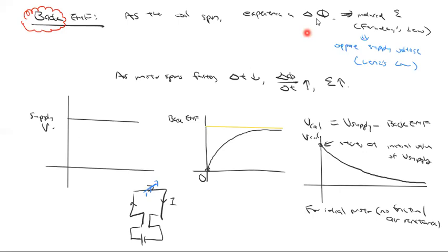So V coil is the voltage across the coil, and I'm saying that it will drop as it starts to spin faster, because conceptually it's like having this battery that's going to get stronger. So it's a variable voltage. This battery wants to push current clockwise. This battery wants to push current anti-clockwise. And if you spin fast enough in a situation where there's no friction, then these voltages will be equal. So the voltage across the coil will be 0.